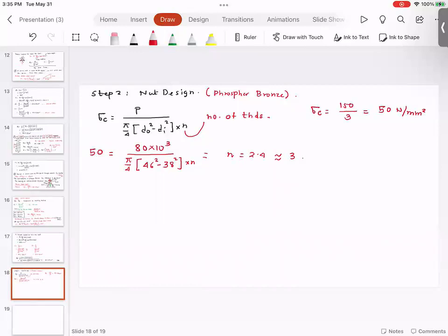Please understand, when the nut or the screw is designed, initial threads are not complete. They are partial threads. If you have a partial contact between the nut and the screw, that joint will not be safe. So at minimum, you need to have 3 threads in complete contact.